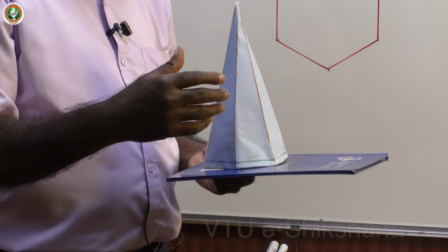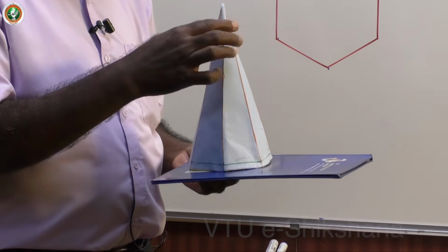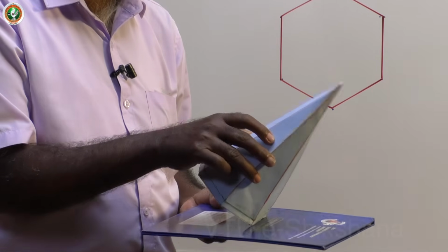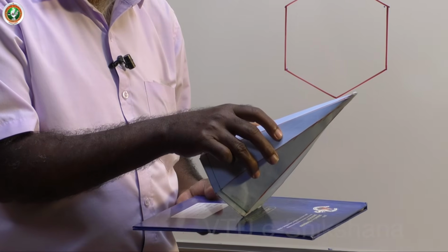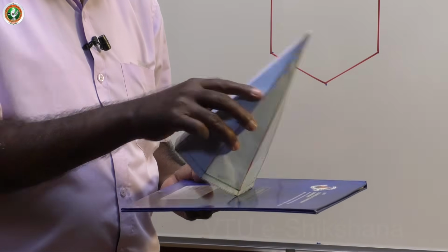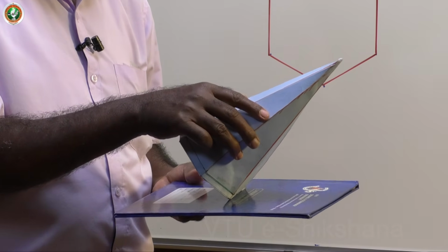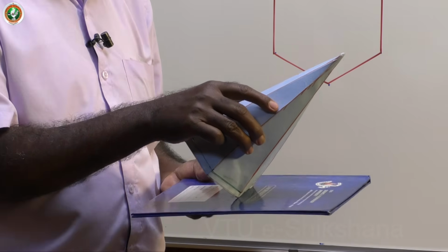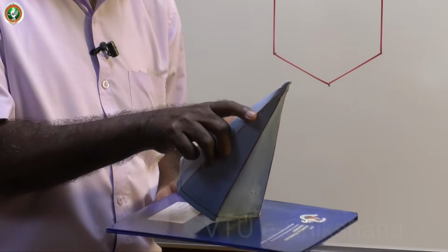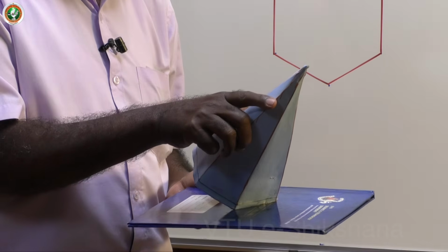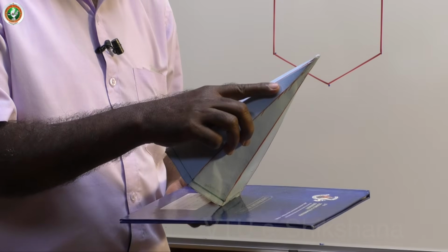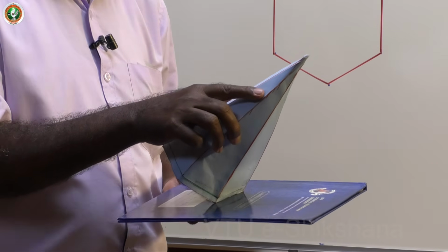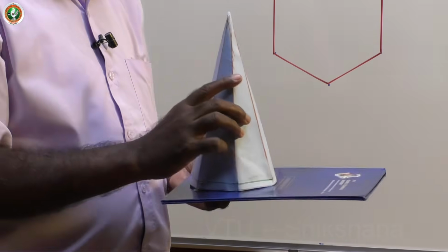Once you draw the front view in this position, you will get this as a line. You can incline that line with respect to the given value. Say the slant face is inclined at 50 degrees to HP. First position, second position. Then they can give inclination to the base edge on HP or to the axis itself. So I have given axis inclination now: first position, second position, third position. So axis inclination can be given, or the edge on HP is inclined some degree to VP. Then true length and inclination. Here you consider beta because the axis reference is there. Okay, now let us work that out.